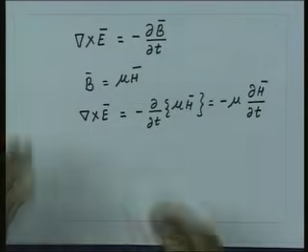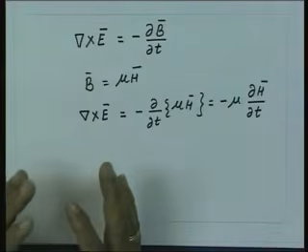So, essentially what we saw is that we have these 4 basic physical laws, the Gauss law applied to the electrical charges, the Gauss law applied to the magnetic charges, the Ampere's circuit law and the Faraday's law of electromagnetic induction, and we write these 4 laws in the mathematical form using the vector algebra and the theorems which we have discussed. These 4 laws can be written in the integral form, but by applying these integral theorems, the same laws can be written in the differential form.